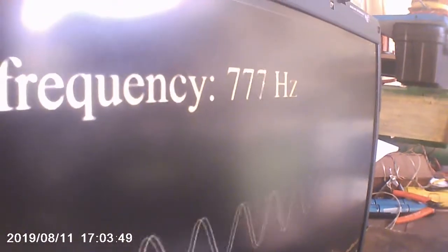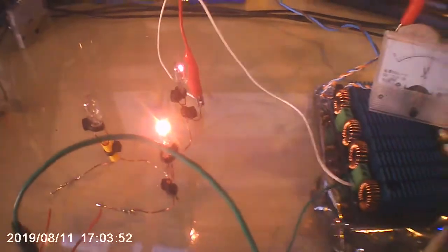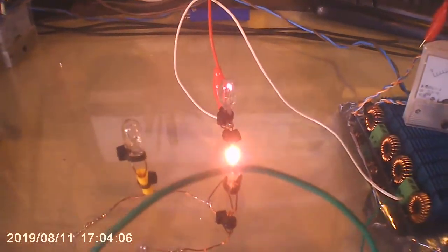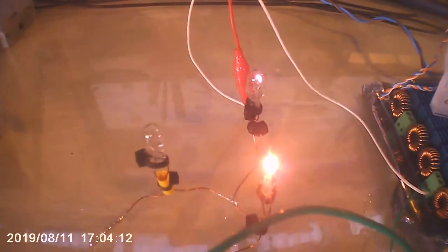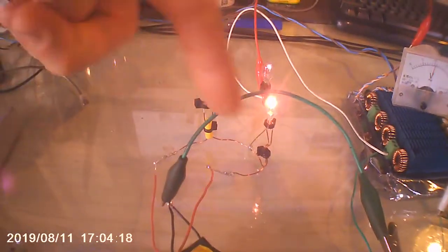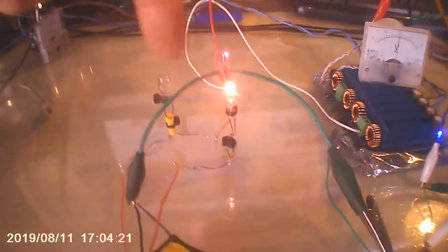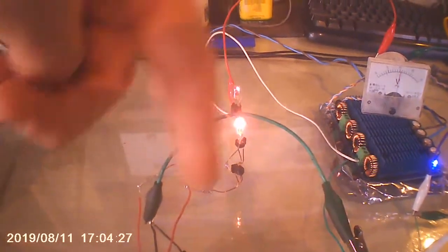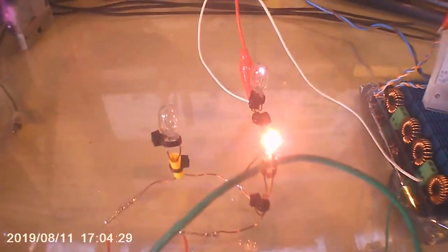at 700 Hertz are not doing what we might expect them to do. So we seem to have some power oscillating around in circles around this transformer, and the loop of light globes, instead of going right through the circuit and back out again, we have some kind of resonant loop of power going on here.